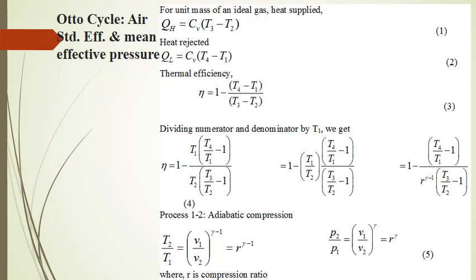And the pressure is varying from almost 1 bar or even slightly lower to 70 or 80 bar or higher, depending upon the capacity of engine and compression ratio and many other factors. So you can see the range of operation, 1 bar to 70 or 80 bar, or you can say temperature 300 Kelvin to 2000 Kelvin or 2500 Kelvin. So even then, these parameters Cp, Cv, gamma, R are assumed to be constant. So that is the assumption, mainly to simplify our